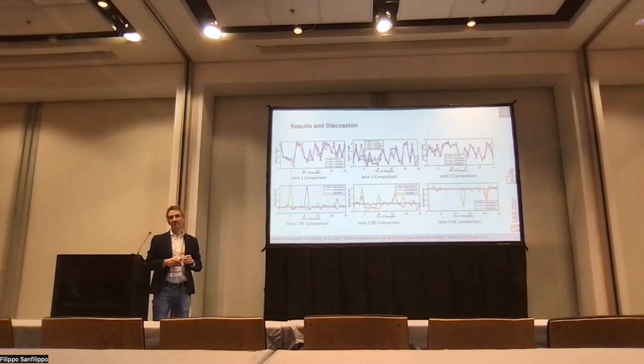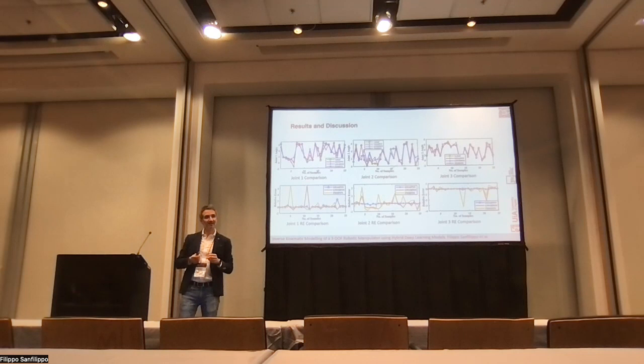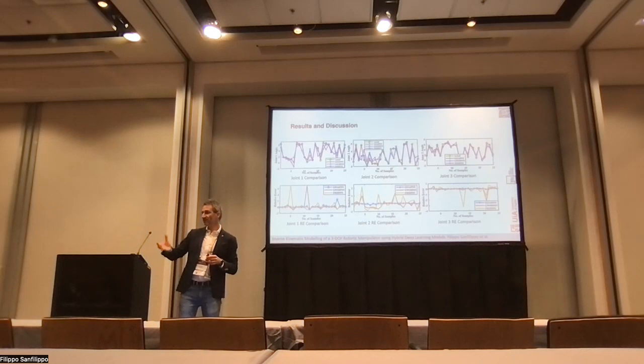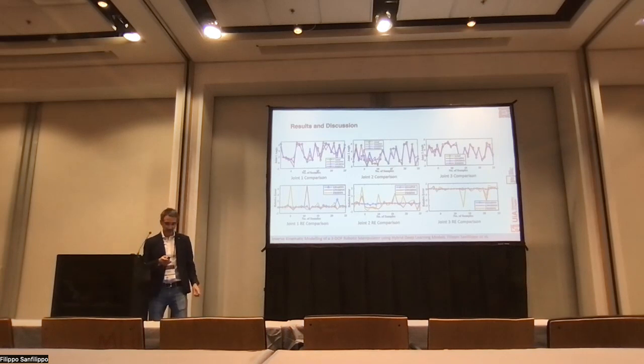There are strategies that we can use to minimize these problems. So for example, we can add the concept of task-oriented manipulation. If I am going to grab a coffee cup with a robotic arm, there is no reason for me to grab it this way, because I cannot use it. So it's normally better to eliminate some of the possible solutions, so I reduce the singularity problem.